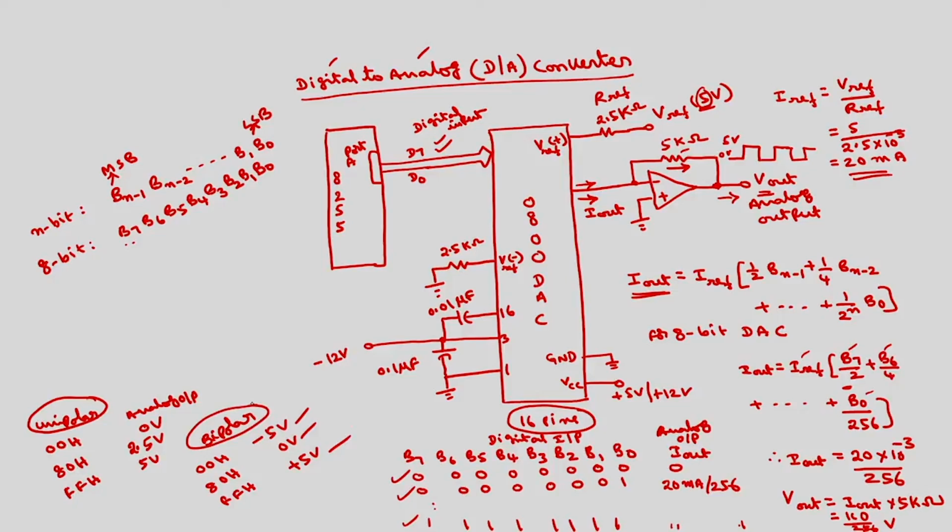Here if I want to generate 0 volt, 5 volts, I will take the reference voltage as 5 volts. So if I send here all zeros over this data bus, you will get 0 volts on this line. You call some delay, then again you send FFH, you will get 5 volts. So I have to program this port A whose address is FCH and controller register address is FFH.